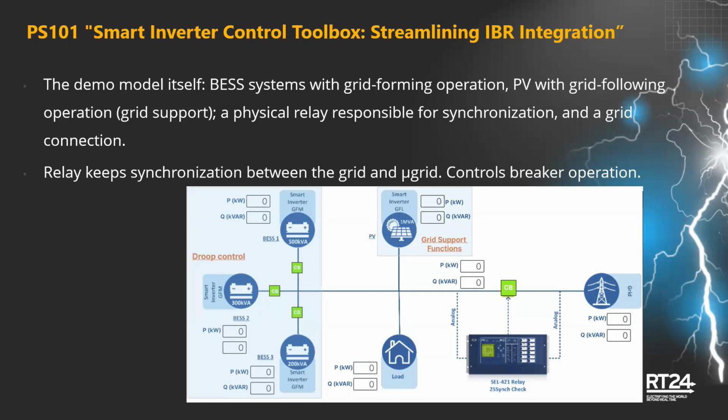And so in this demo, what we're going to demonstrate is when I close that grid connection, you'll see that the relay will basically be in charge of the closing, such that it is a synchronized closing. And then it also will provide and control the PV to provide the appropriate support so that it gets to a nice even level on both sides. And that's the goal of this demo.